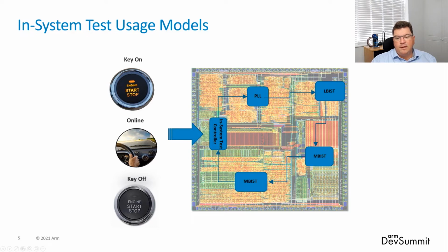With this, especially in the automotive space, the requirement is for a very short test time. If you can imagine, these tests are being run at the startup of a vehicle. So the requirement there is to get the vehicle ready for operation as quickly as possible. So here we tend to run as many tests as we can in parallel, and we may also run a basic level test just to ensure the device is operationally correct. But we need to do this and also meet the aggressive test time requirements.